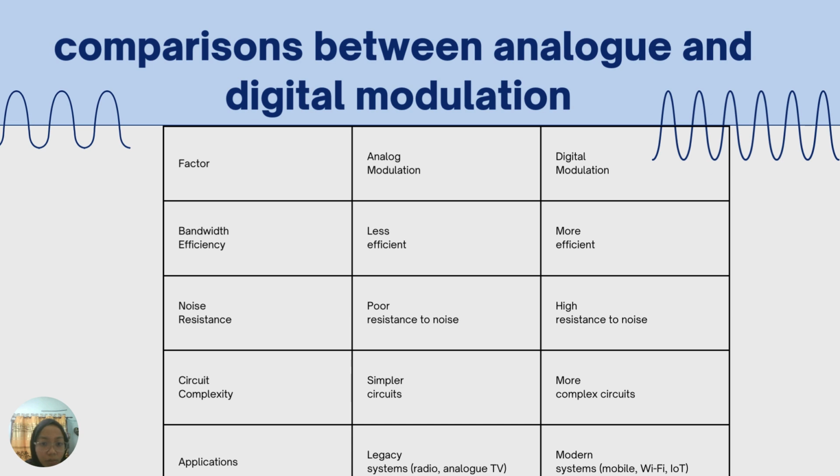On the other hand, more complex circuitry becomes necessary in the case of digital modulation, which includes analog to digital converter, ADC, digital to analog converter, and complex signal processing. Error correction and synchronization further increase complexity in design. Contemporary cellular phones make use of complex digital modulation techniques, requiring high processing power. Analog modulation, however, is simpler in circuitry.